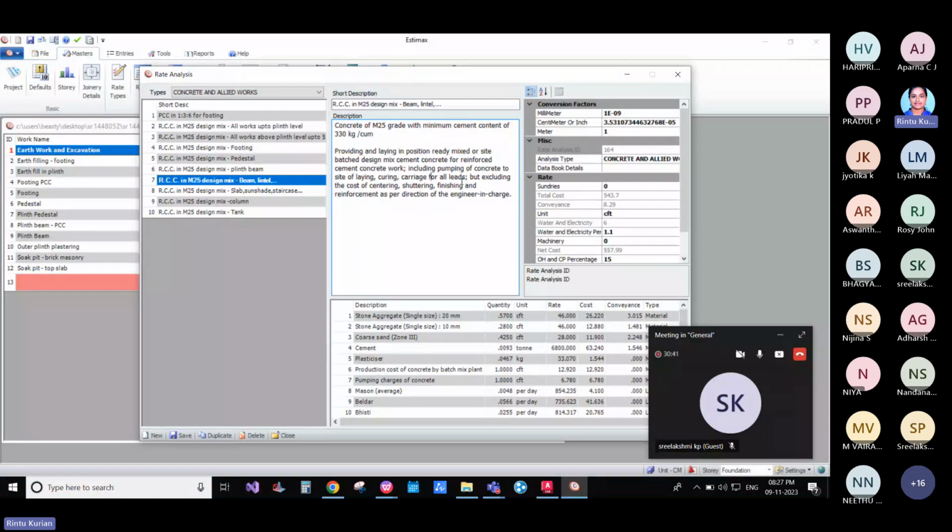Now here we have the option for conversion factor. Conversion factor is nothing other than a value you put to convert the drawing unit, the data collected from the drawing, to the output unit you require. For instance, we have seen that we are inputting the value in centimeters, but our output is in meters. We can input the value in centimeters and get an output in feet. All these are possible if you change the conversion factors. That is handled in this particular area.